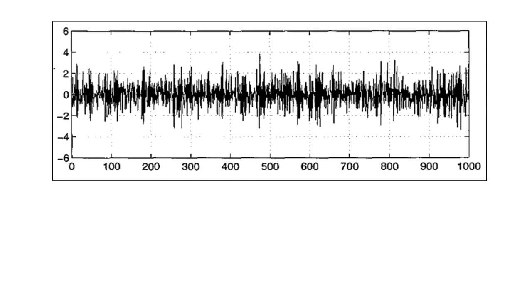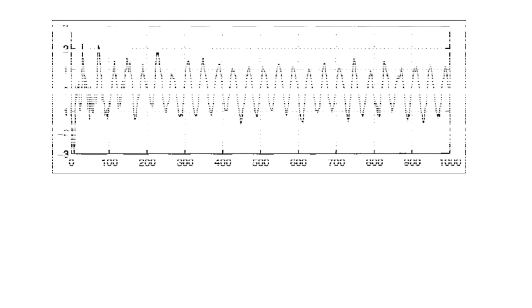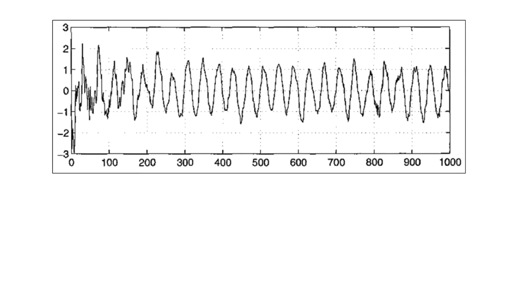Let us use a 12th order adaptive noise canceller with coefficients updated using the normalized LMS algorithm. The normalized version of the LMS, least mean square algorithm, we already covered in the previous video. The estimate of the desired signal d of n produced with a step size of, for example, 0.25 can be shown with this figure.